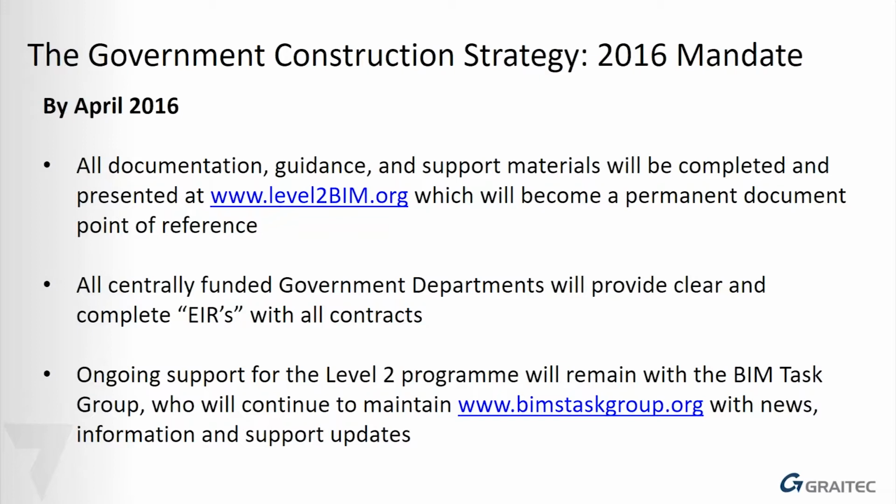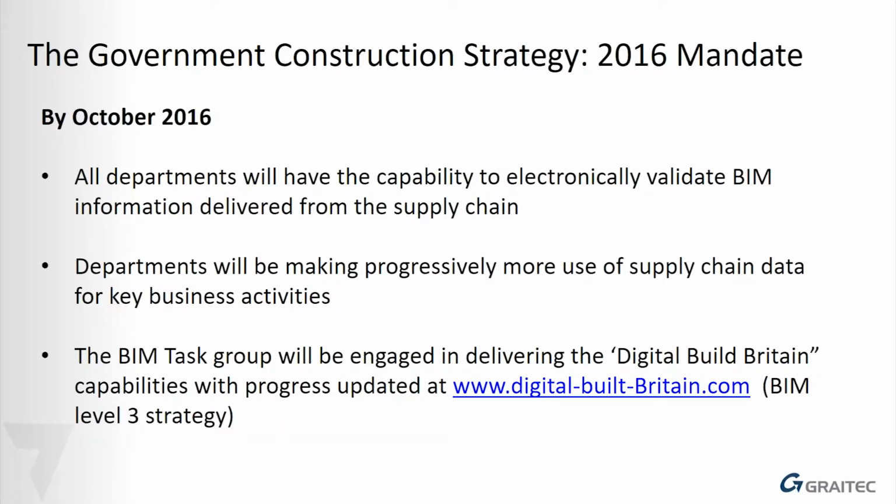They've also dictated of the government that all centrally funded projects will require a BIM Level 2, and they will complete what we call an EIR. So the EIRs, and I'll talk to you a little bit more about what an EIR is later on, which is the Employer's Information Requirement, basically means that from your point of view as maybe the main contractor, where you're getting your supply chain involved and you want certain information provided in the model, the EIR will allow your supply chain to understand what information you are asking for within the models.